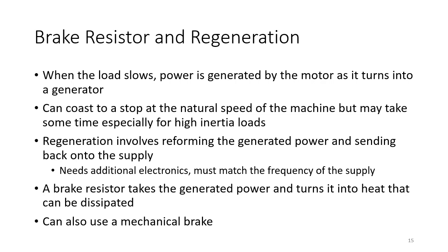Those additional electronics are needed to effectively turn the VFD back to front. So instead of supplying power from the mains to the motor, the VFD now has to supply motor power back into the mains. So often that involves a parallel set of electronics, so we're effectively doubling the cost. And then there's additional electronics which are required to match the frequency of the supply. We can't just put AC voltage onto the supply. We've got to match the frequency of that supply, otherwise we could seriously affect it. So regeneration is good, but it means that you have to pay a lot more for your VFD.